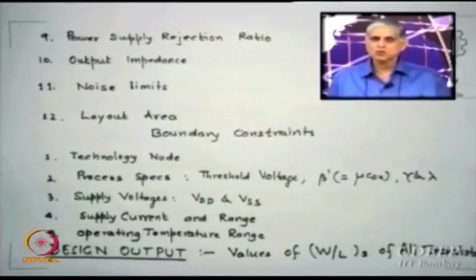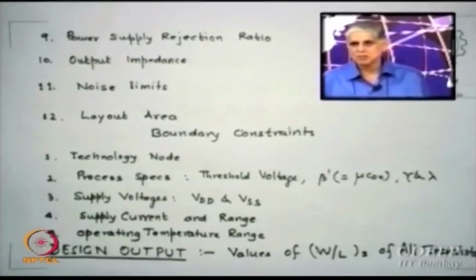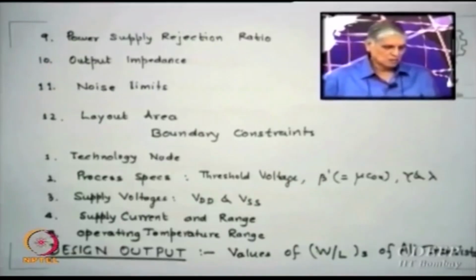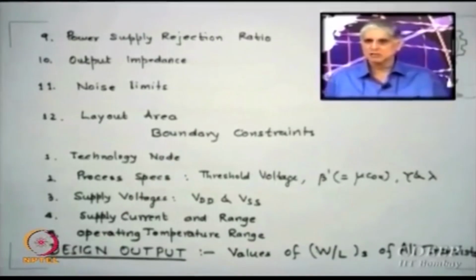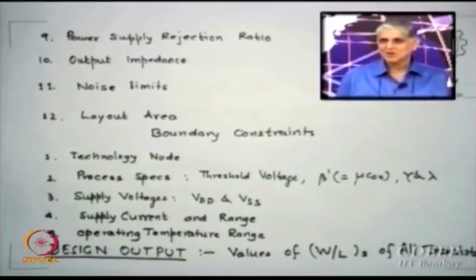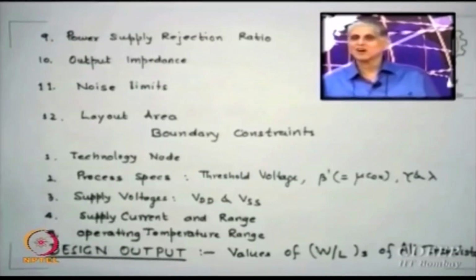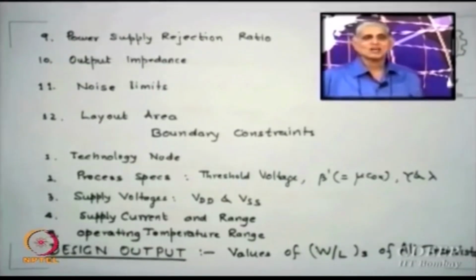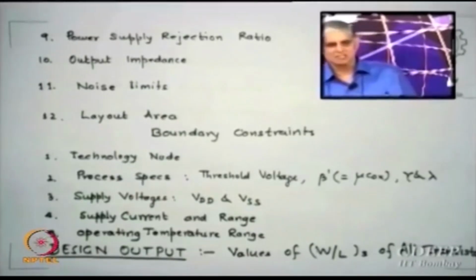You also ought to know the substrate bias parameter gamma, and the saturation parameter lambda. Some data which I have given shows that lambda is also a function of length. So at whatever length you are working, even if the node is anything, you must figure out what lambda is there. Generally SPICE allows you to know different lambda values at different lengths.